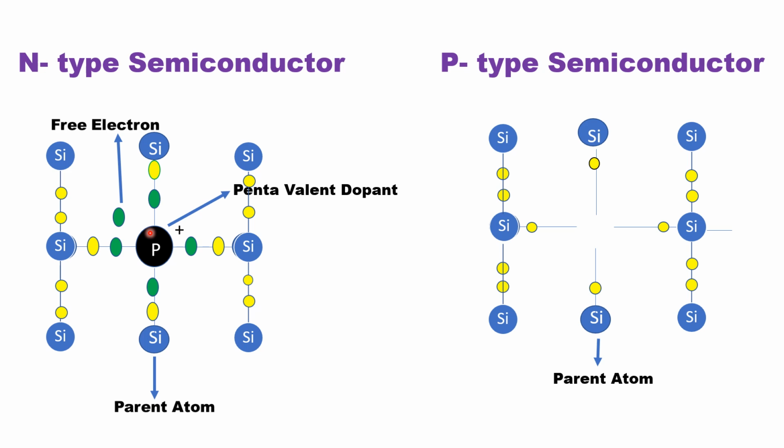In this type of semiconductor, the electrons are contributed by the donor and the thermal generation process. So, the electrons are the majority charge carriers, while holes are only generated by the thermal process. So, the minority carriers are holes in N-type semiconductor.